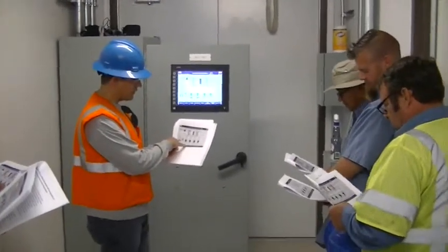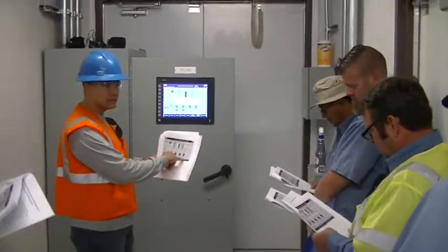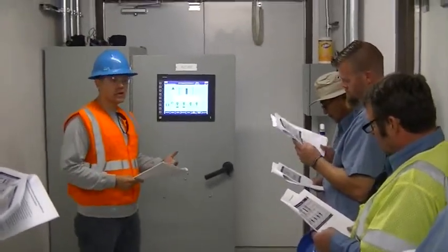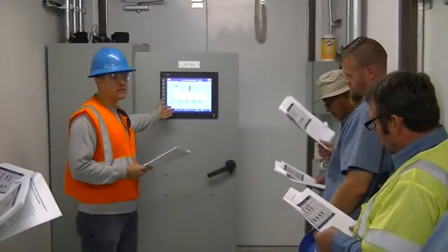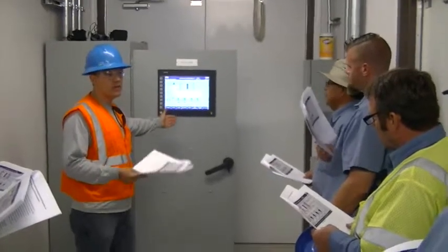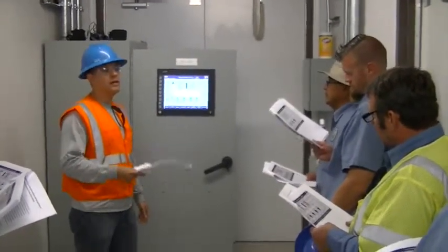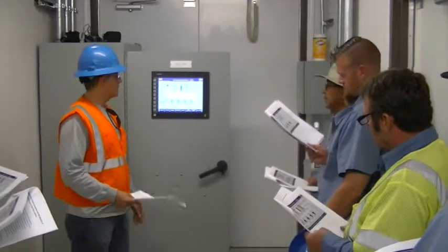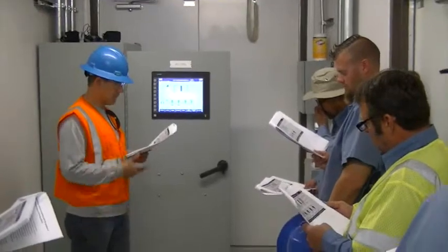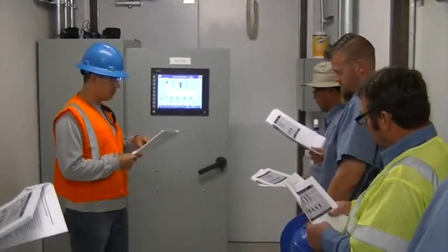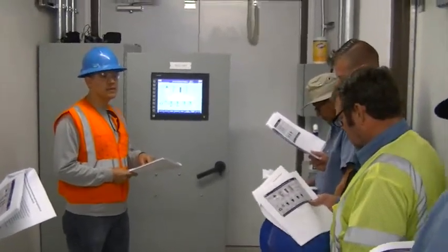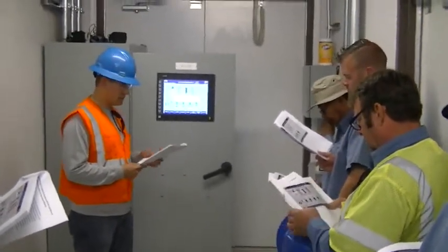So you have your low flows underneath there as well. And that condition is if your pump is called to run and you don't get a flow signal, you're not getting above 200 gallons per minute, it will give you that low flow. It'll lock that pump out and then try the next pump. So it'll keep doing that, but once it tries it, you have to reset it. And then the bottom one below that is on the backup PSHL, which means that you either lost your discharge pressure signal or there were coils that put it in that condition.